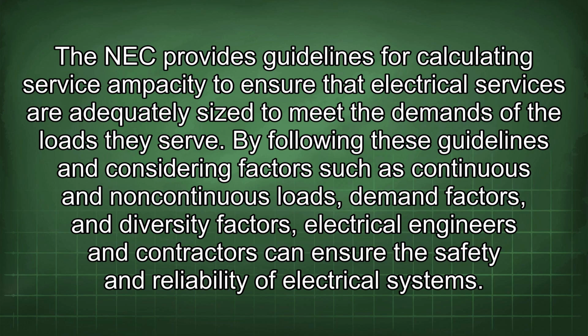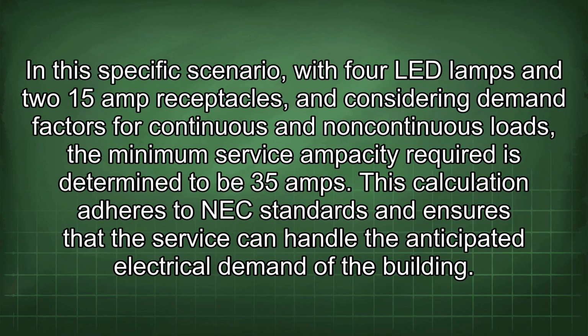By following these guidelines and considering factors such as continuous and non-continuous loads, demand factors, and diversity factors, electrical engineers and contractors can ensure the safety and reliability of electrical systems. In this specific scenario, with 4 LED lamps and 2 15-amp receptacles, and considering demand factors for continuous and non-continuous loads, the minimum service ampacity required is determined to be 35 amps. This calculation adheres to NEC standards and ensures that the service can handle the anticipated electrical demand of the building.